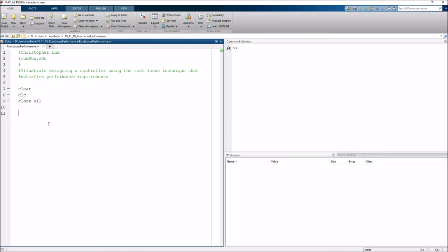All right, so I've just started myself a little script here where we can go ahead and first define the plant. According to our transfer function that we're looking at here, I think this is an appropriate numerator for it, and this is an appropriate denominator. I think it was S squared plus 0.01 S plus 0.0025. So there we go. Here's our transfer function now.